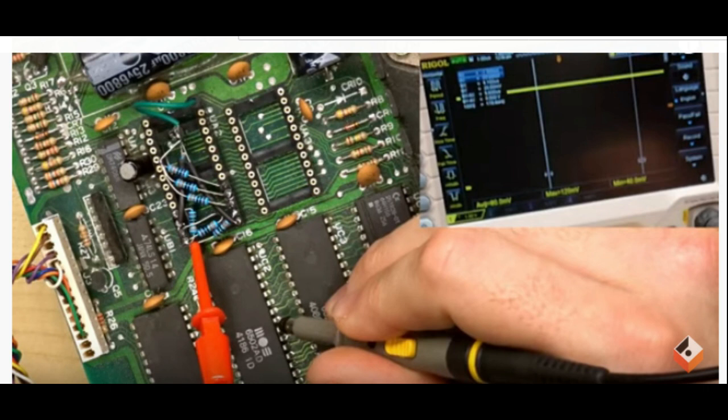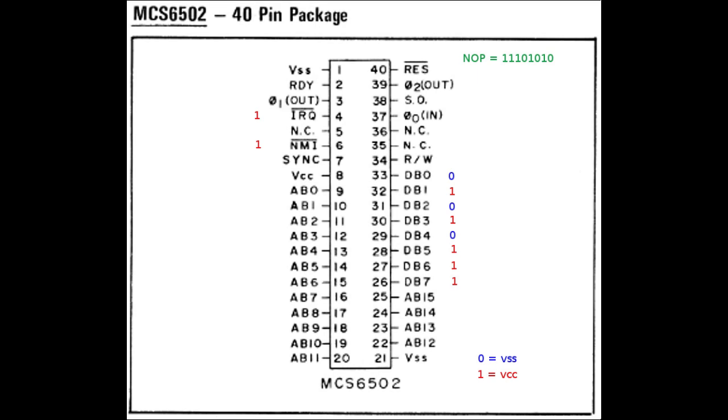That's why, as you've seen in this picture of the video, he had to use resistors on each data line to avoid damaging other chips that might be driving the data bus at the same time. Of course, in this case, Adrian had no other choice because it's the 6502 on that 1541 board that was soldered directly on the PCB without a socket.